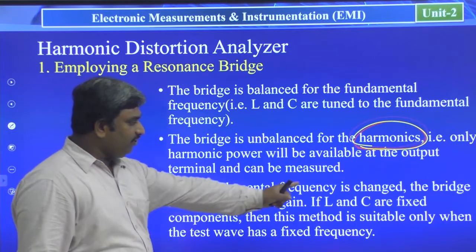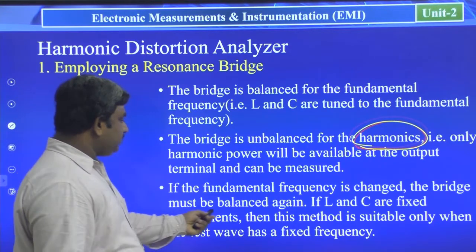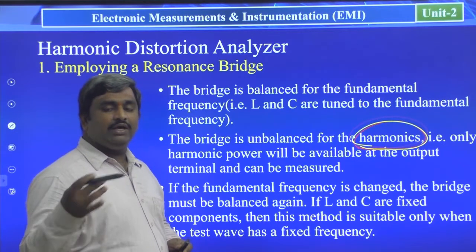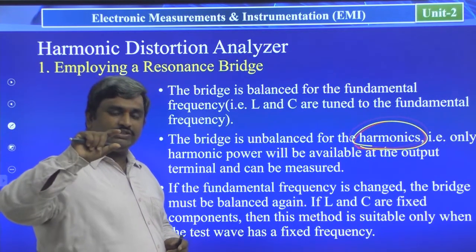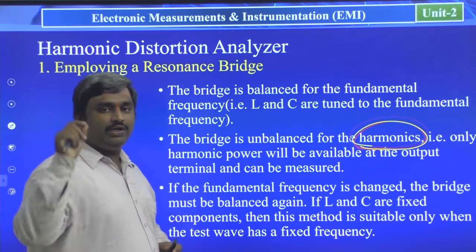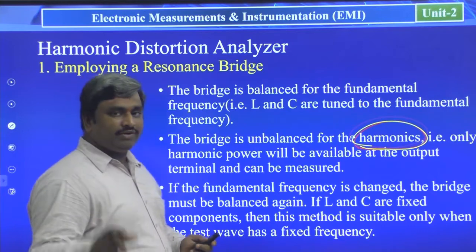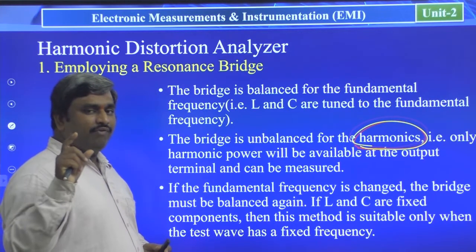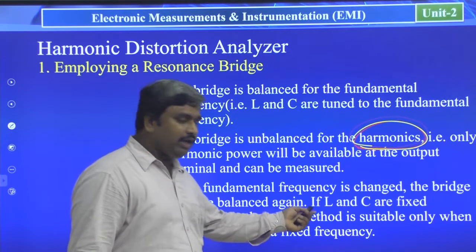If the fundamental frequency is changed, the bridge must be balanced again. If you are changing the fundamental frequency, then you have to change and tune the LC components to get your fundamental frequency. Whatever frequency you are keeping at the input terminals as a test wave, you have to adjust to that frequency.